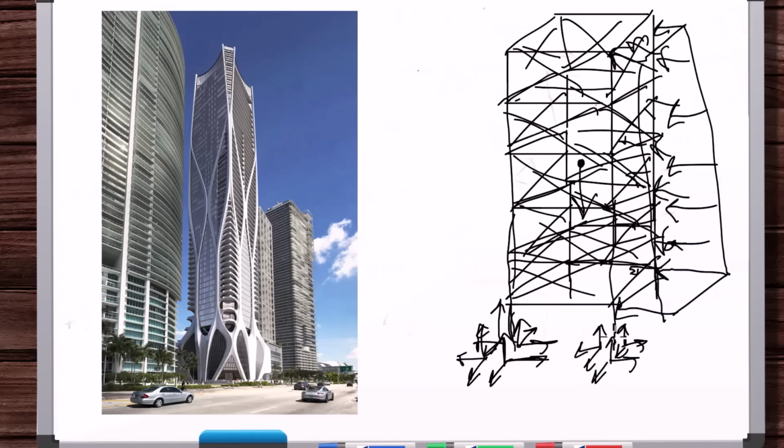But what you can also imagine is that getting the machining tolerances as accurate as you can is important. If you don't drill a hole at the right location and you put all your bolts down, and one bolt is butted up against the surface while the other bolts have more of an area between the bolt hole and the bolt, then that bolt that's more butted up against the surface is going to take more of the load.